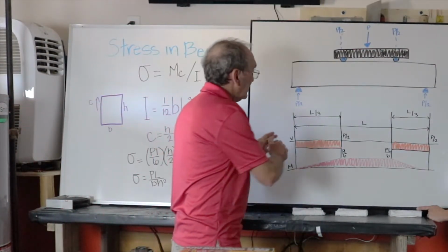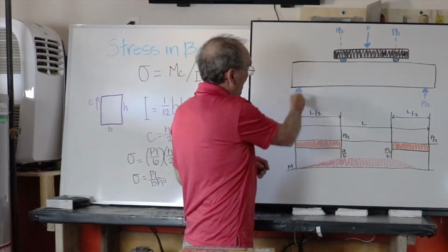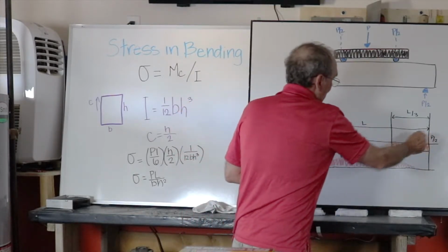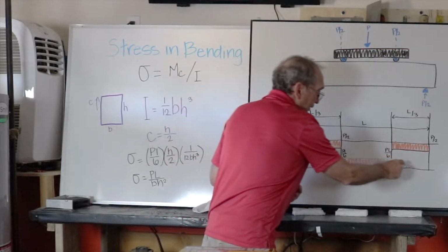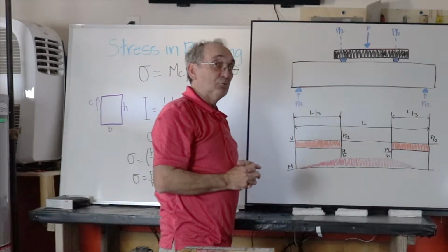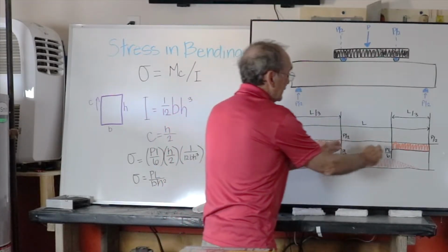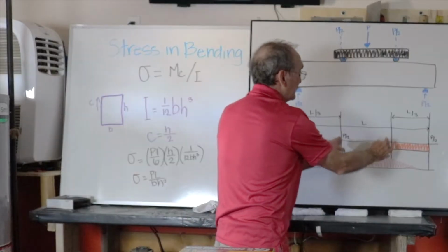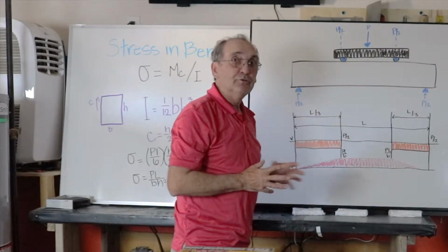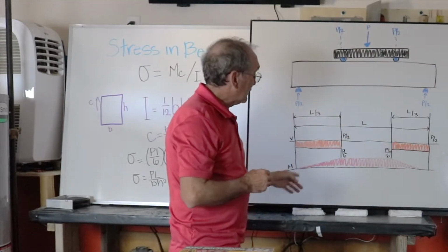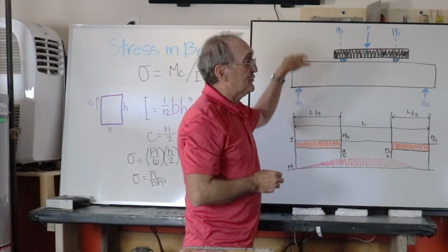So back here, this is very common. This is our shear diagram. We integrate our load, and it gives us our shear diagram. We integrate our shear, and that gives us our moment diagram. Now let me explain why this is so incredibly clever when they set this up. Note that in the shear diagram, there's no shear in the middle third of the beam at all. The way this is set up, it eliminates shear in the middle third. And note that the moment is maximum in the middle third of the beam using this boundary condition setup.